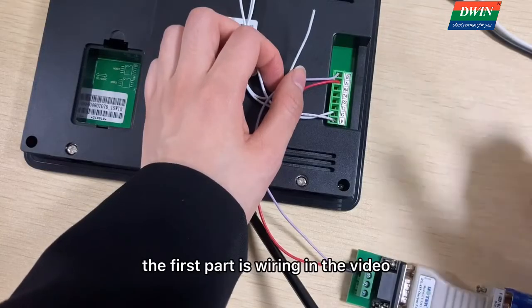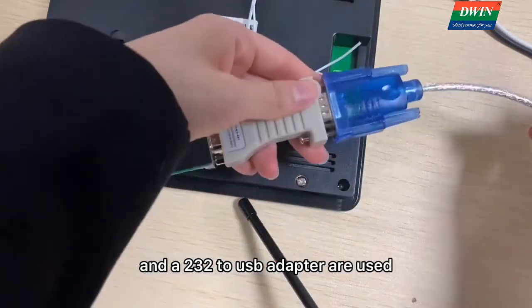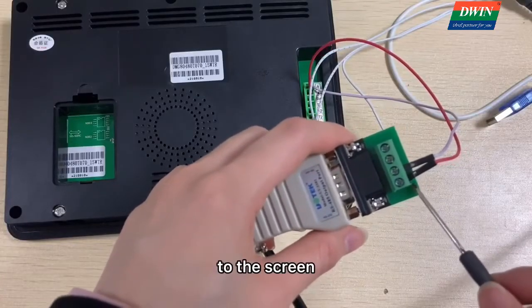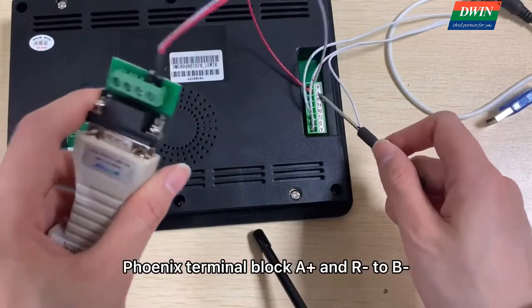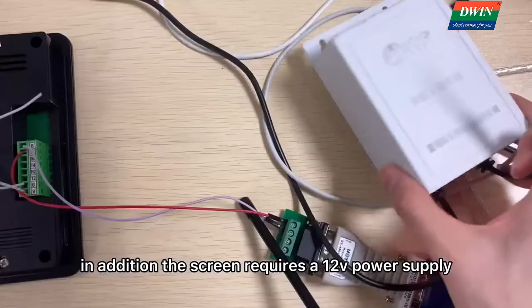In the video, a 485-232 adapter and a 232 USB adapter are used. Connect 485 R+ to the screen's Phoenix terminal block A+, and R- to B-. In addition, the screen requires a 12-volt power supply.